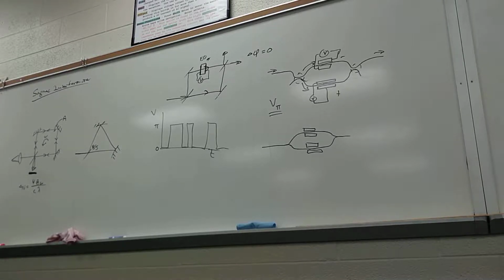Well, once it gets to be this size, it's starting to get big. So instead what you do is take all of this and replace it with fiber and wind that fiber around many, many times, maybe 2 kilometers of fiber there. And now, let's say you go around m times, so the total area is m times the area of the coil. And now you've got a fiber optic gyroscope.